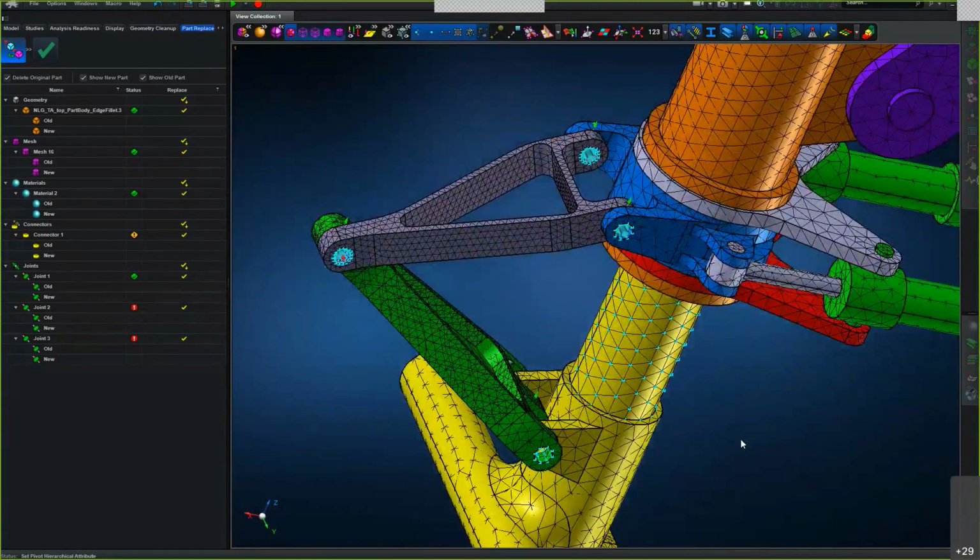I think that's all the questions I have. Let me check. Okay, there is one more to further explain my glue question. If two plates overlap, by default, all the overlapping elements will be glued. Will I be able to delete it and only select the edge of one surface, connect to the other surface to represent an edge weld?